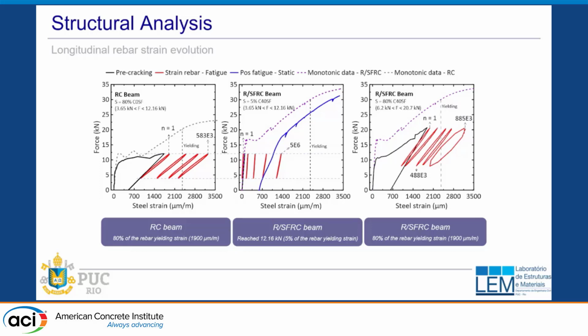This is plain concrete, which means that after the cracking of the concrete, basically now what you're doing is primarily you're doing the steel. The steel rebar is the one that's carrying all of the force and resisting the fatigue. So it is the steel strain that's measured in this range.